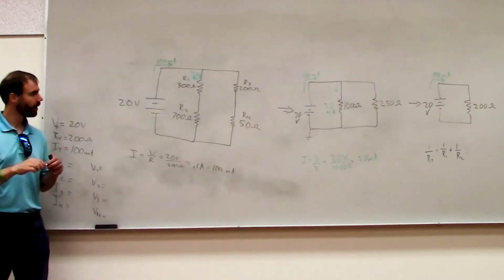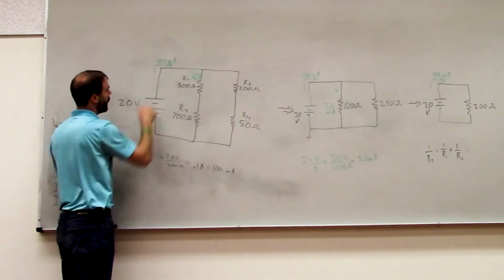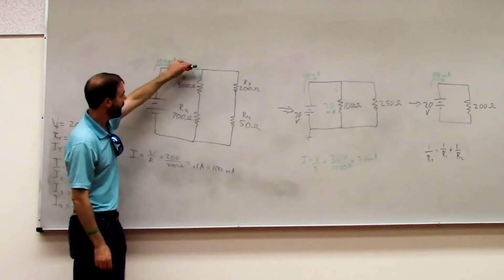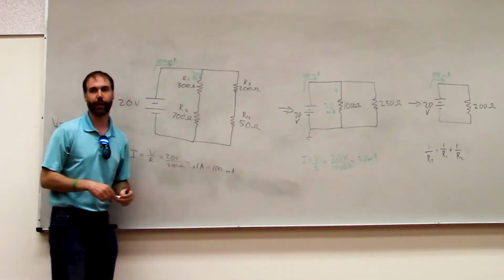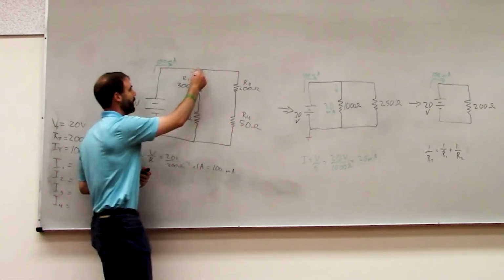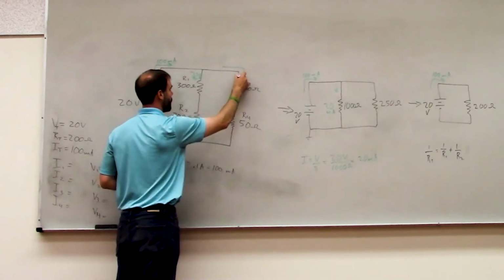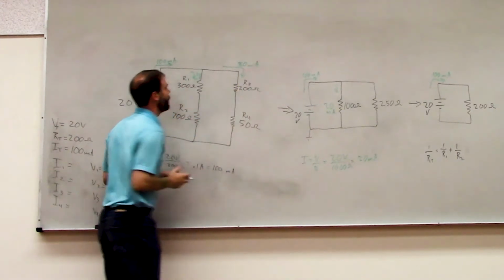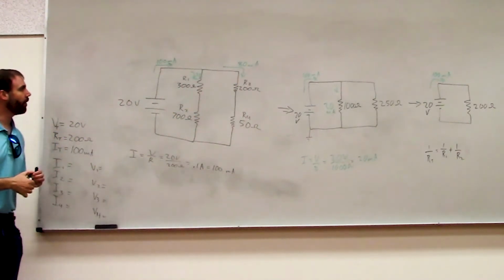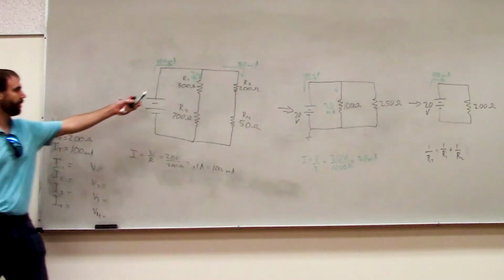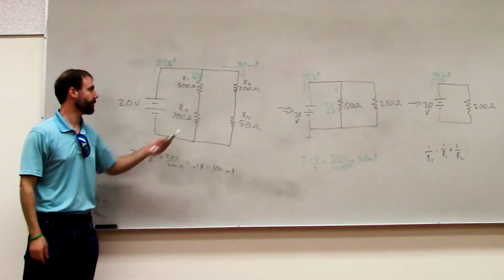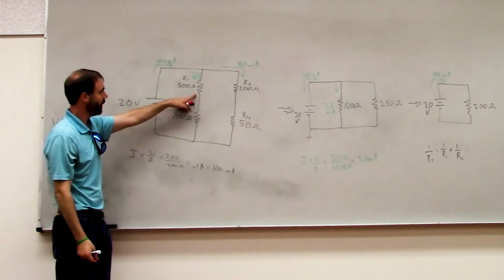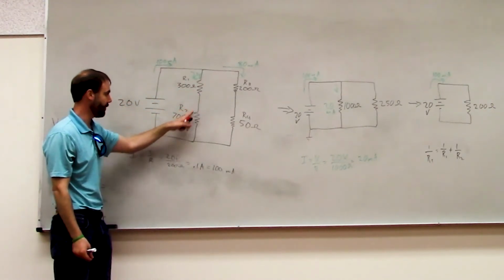Okay? So if we have 100 milliamps flowing in here and 20 of it come down this way, how much is left over to go down the other branch? 80, exactly. So we have 80 milliamps flowing over there. So now we can use that information to fill in the current for each of the resistors, right? Because we know if we've got 20 milliamps flowing into this resistor, it doesn't have anywhere to go except into the next one.